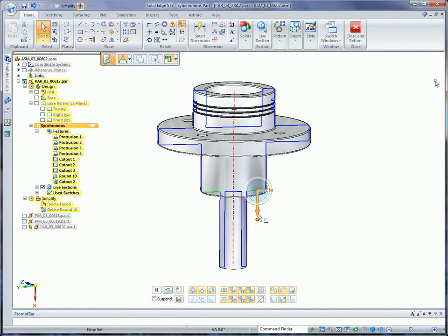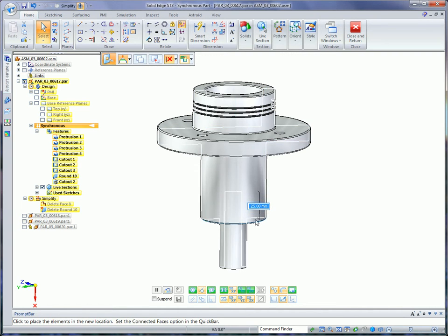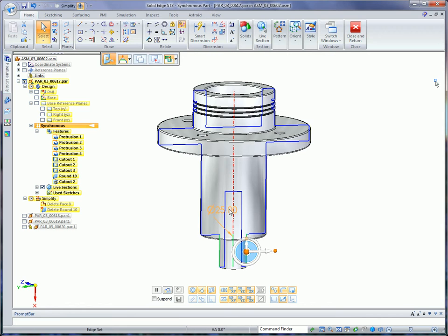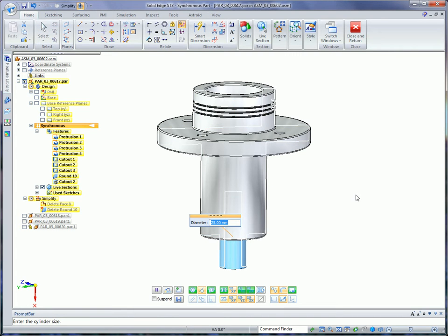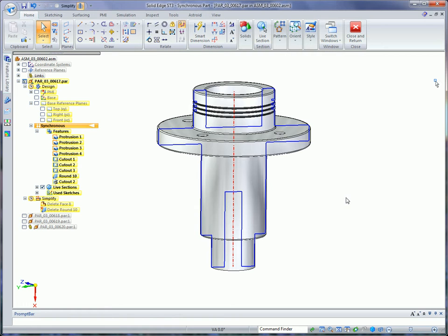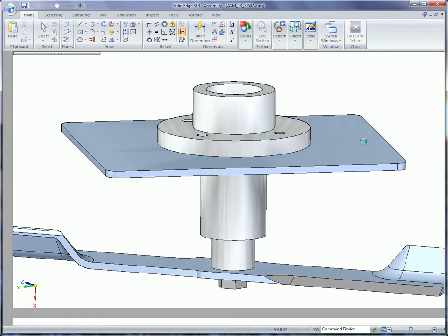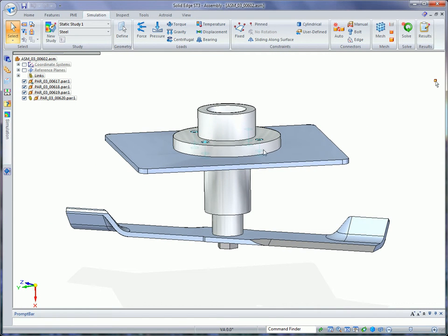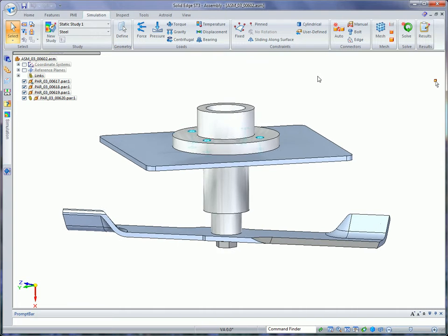I want to use my steering wheel to simply pull this down a little bit to make it stronger. I'm going to bring it down about 40 millimeters. And then finally, the diameter that had all the stress, it's only 25 millimeters in diameter. So I'm going to fatten it up by taking it up and maybe key in a value of 40. So you can either scroll the value or you can key a specific value in. When that's done, we can go back to our subassembly, and you'll notice that even though we're still using the simplified version, the diameters have all been updated.